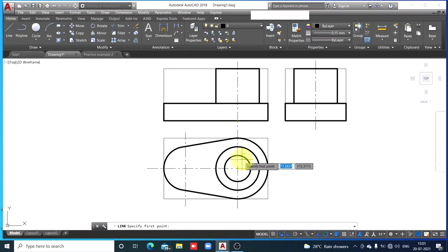Again, it is a hole, but a circular hole. In top view a circle, in the remaining two views a rectangle. But it is a hole. It is surrounded by material. Therefore, in the front view and side view, it will be hidden. So how to draw it?